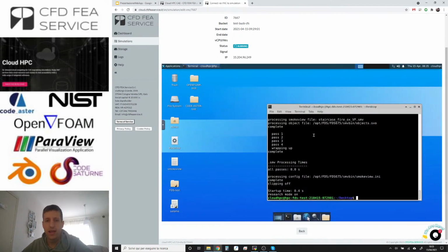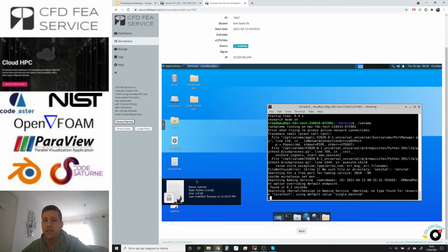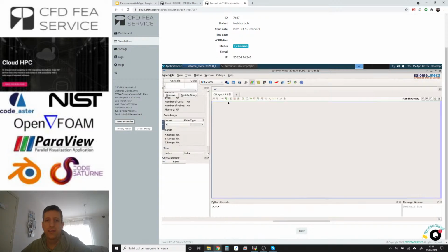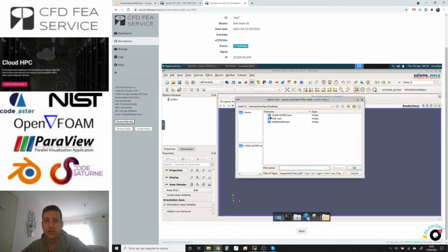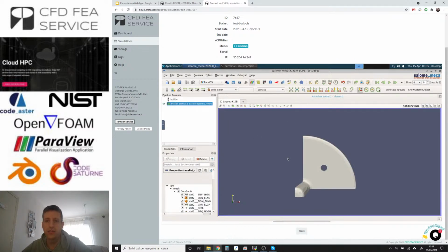Okay. In here, it is possible to execute Salome. There is a shortcut in here to be executed on the desktop. This will allow me to open Salome. Obviously, I need to enter into the ParaVis submodule. Using ParaVis works pretty much like ParaView. So I just need to open the CodeAster results, open the RMED file produced by CodeAster. I just press apply to open it, and these are the results which I can see.